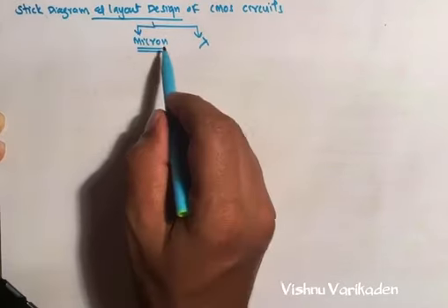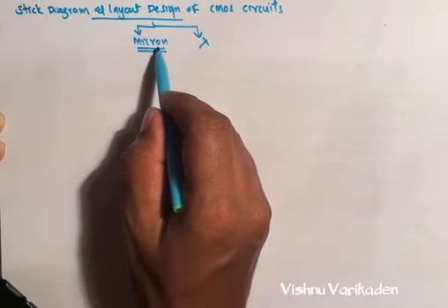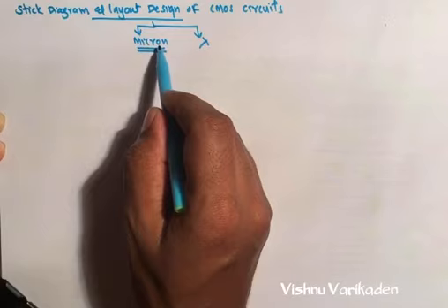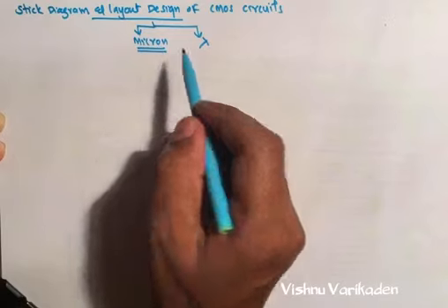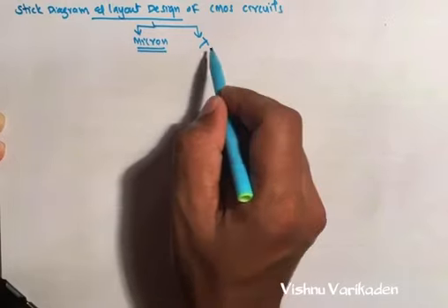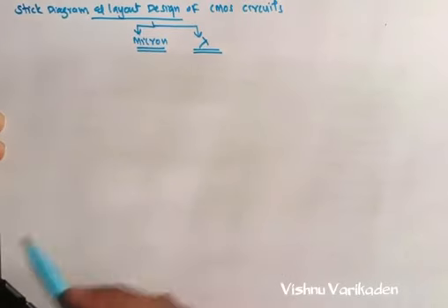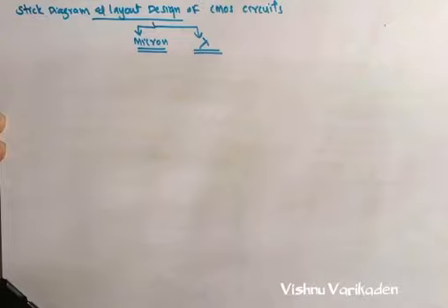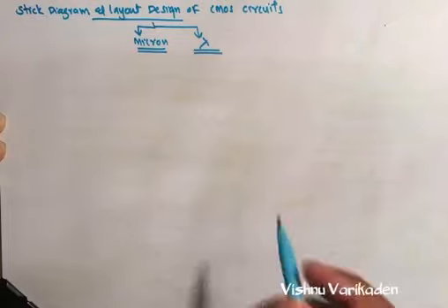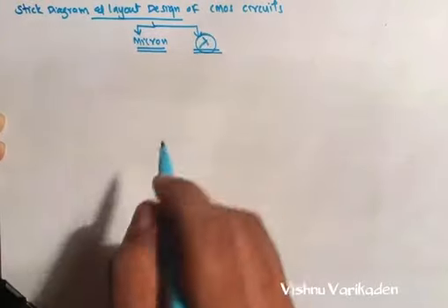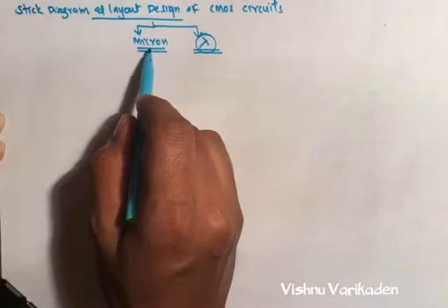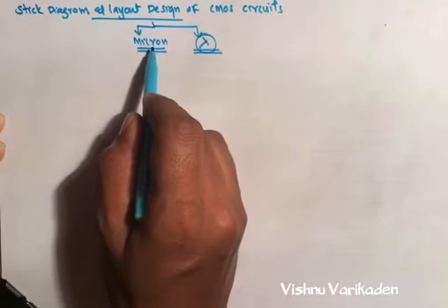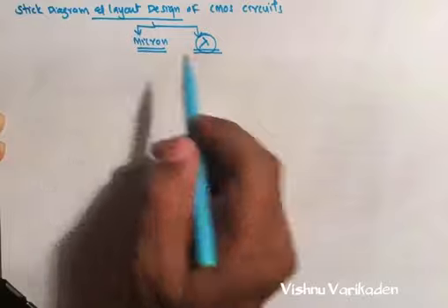In industry, we now use the micron based design rule in IC fabrication. This is an industry standard. But in the lambda based design rule, we can scale each layer by a lambda value. But in micron based, all terms are standard.